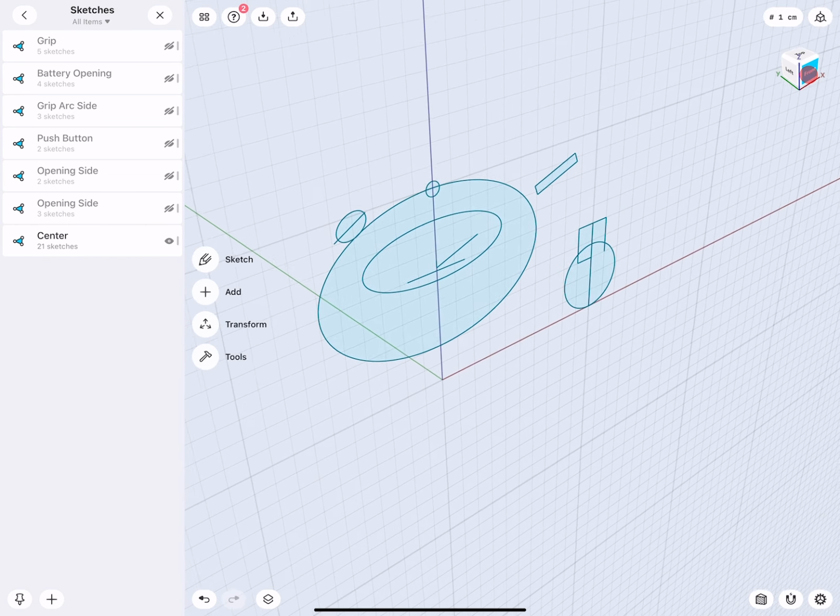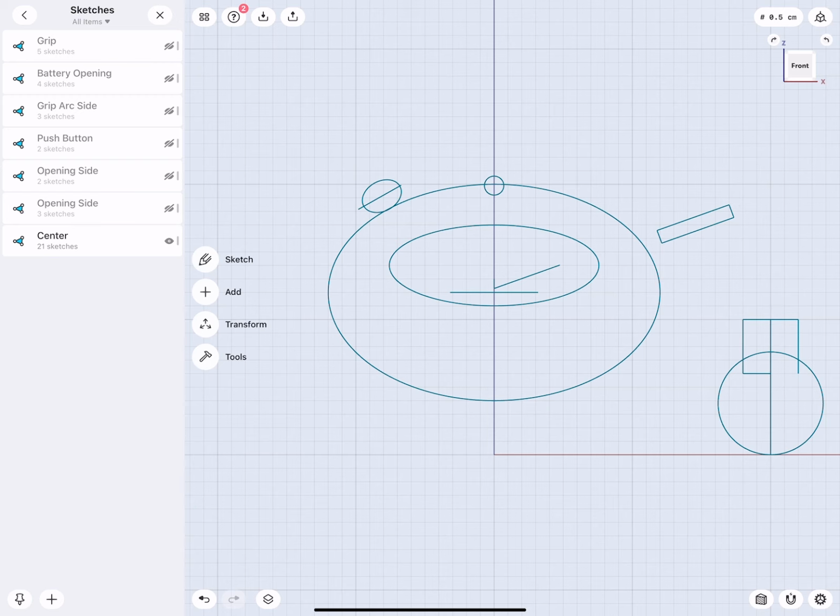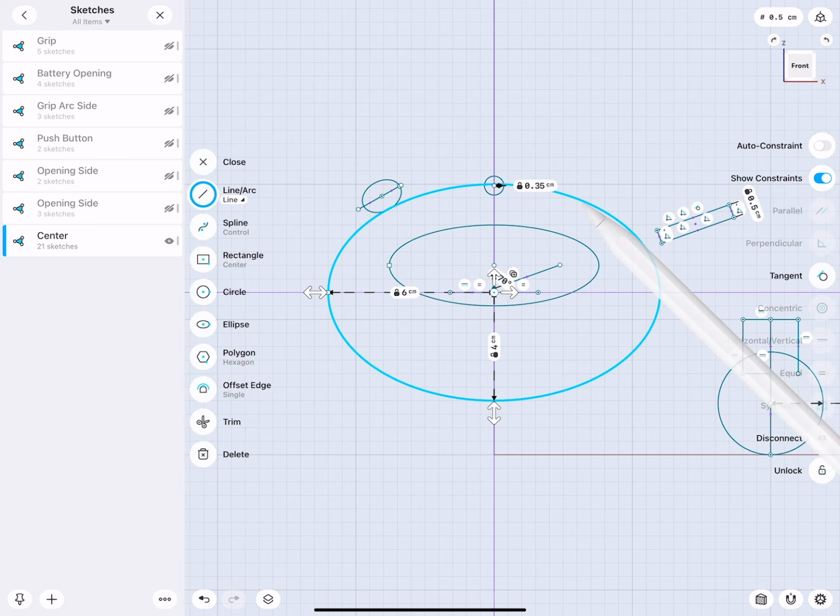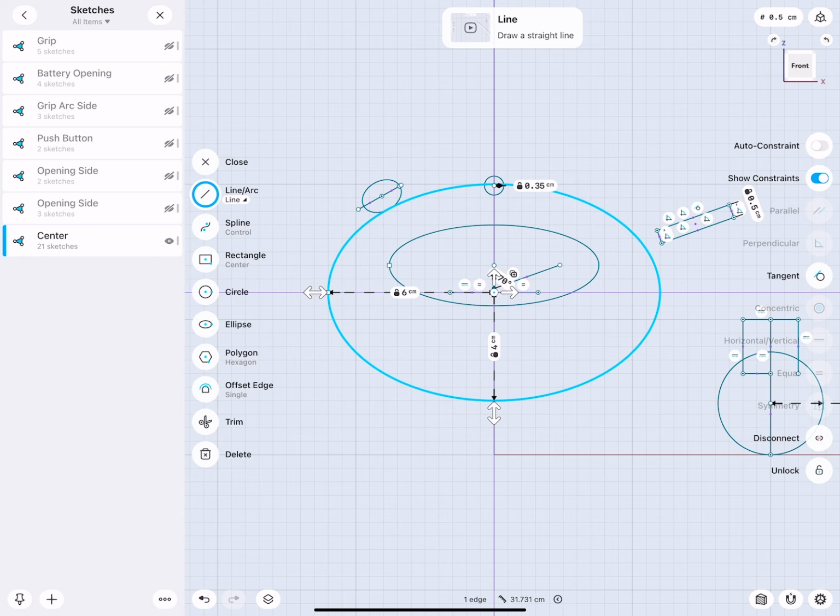And let me explain also a little sketching trick. So we will start with building an elliptical body. It's easy to do. We need an ellipse like this, and then we revolve it. To revolve it, we need to draw a center line. I have the center line actually here. And you see that this line is rather small.